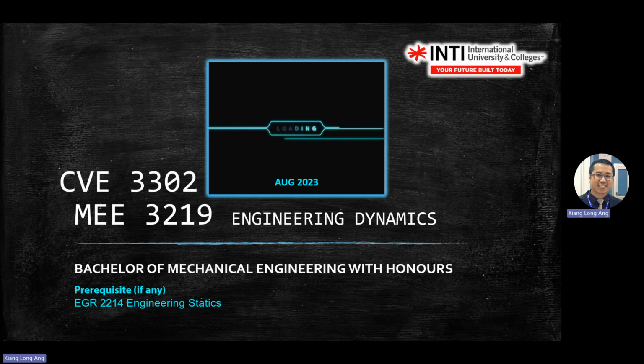Okay, so recap what you learned previously in chapter 1. In chapter 1, you learn about S, V, A, and T. You learn the definitions: V equals ds/dt, A equals dv/dt, and A equals d²s/dt². Combine these two, you freeze the time, and you get A ds equals V dv.